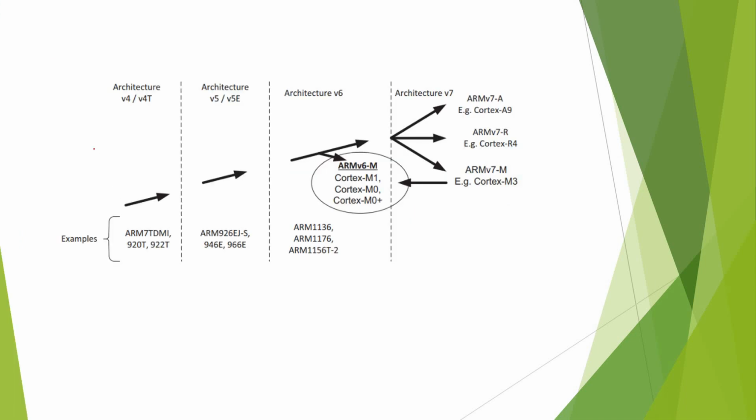So ARM started in 1985, and one of its major goals was to create low-power efficient processor families. To achieve this goal, ARM's decision was to take RISC-based instructions as the baseline for their instruction encoding. RISC-based instructions each execute a very basic and minimal processor operation. Therefore, it doesn't require sophisticated hardware logic and design to get it fully implemented and executing, which means a low amount of transistors are needed for such a design implementation, resulting of course in low power consumption.